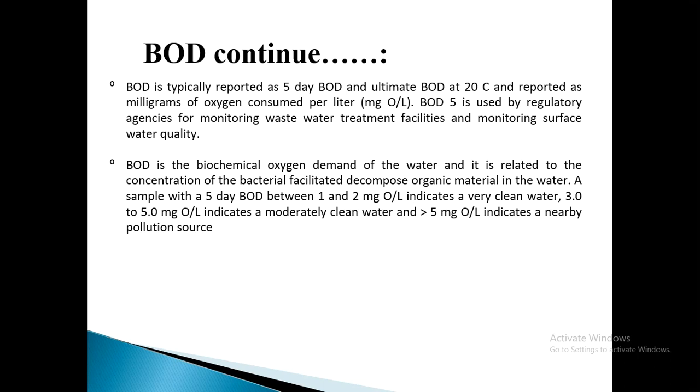And a sample with a 5-day BOD between 1 and 2 milligrams of oxygen per liter indicates very clean water. For example, if we collect a sample of water and on the 5th day its BOD value is between 1 and 2, then it's very clean water.